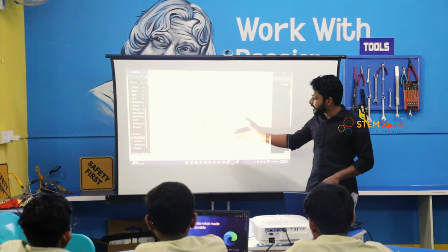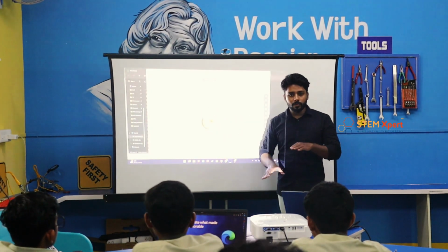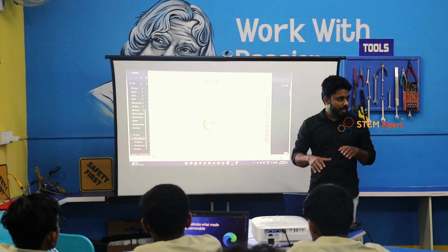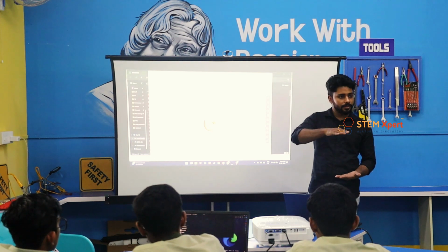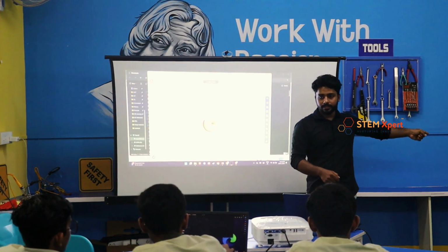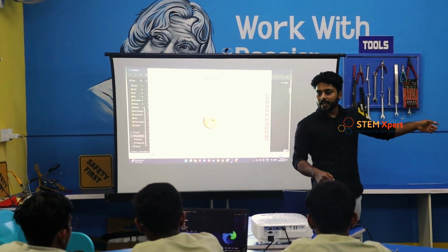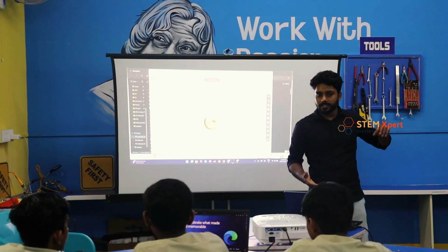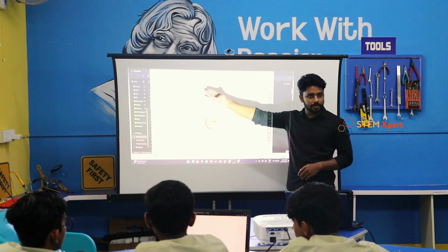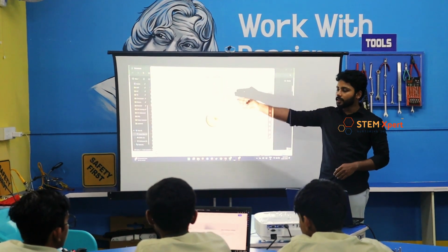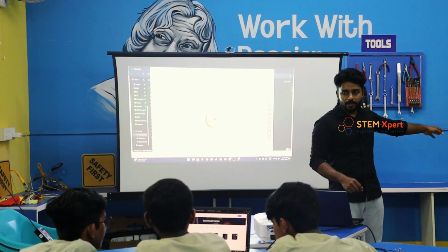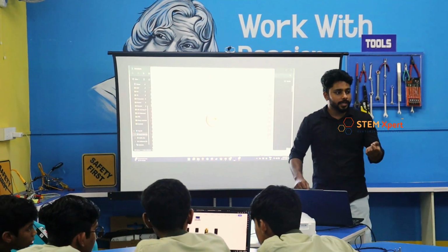We are cutting this model into different two-dimensional shapes, and they will be added like a stack, one by one. That's what is happening in the 3D printer. So we need a sliced format for 3D printing. For that purpose we are using a slicing software, which is FlashPrint, and this FlashPrint is supported by these Flashforge printers. So how can you download it?